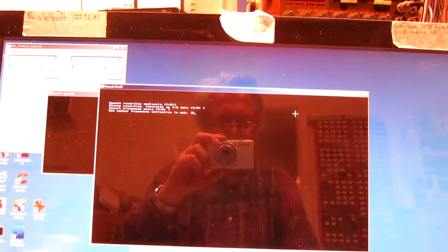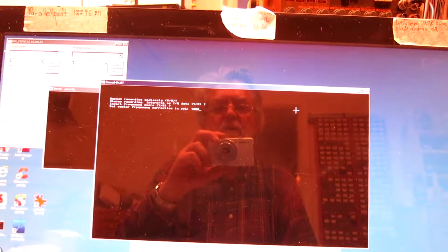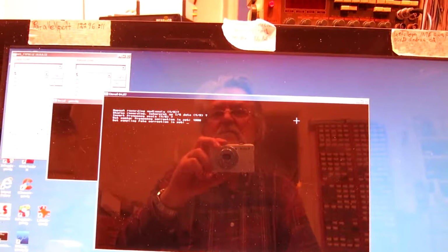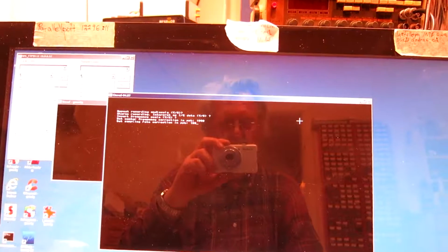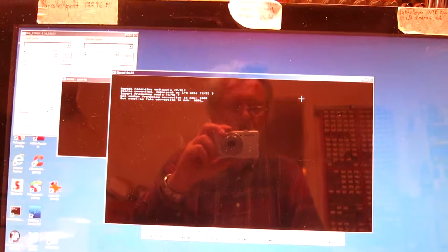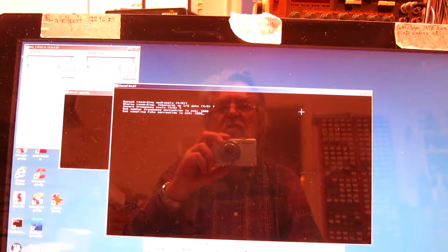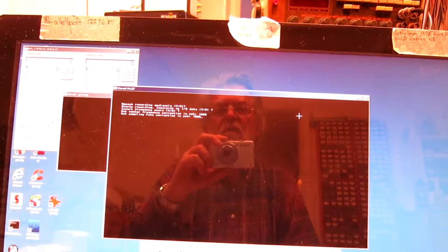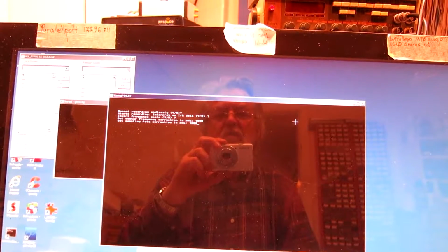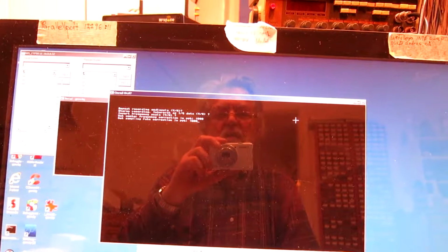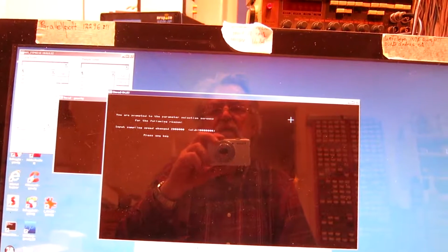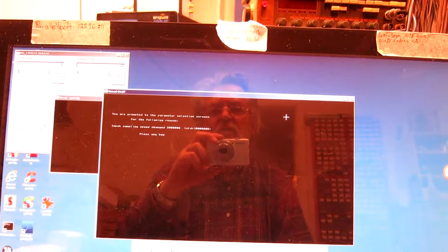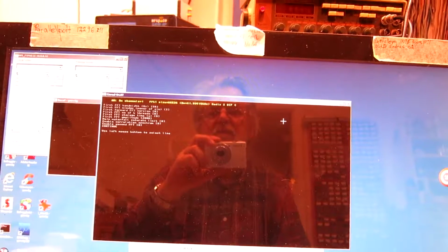That is 1800, 1.8 ppm. Sampling rate correction in ppb, 1800. Now, if I had made a recording with the calibrated unit, I would have had to set the center frequency correction to 0, while I would have to set the sampling rate correction to 1800, I think. Input sampling speed changed. Yes, press any key.